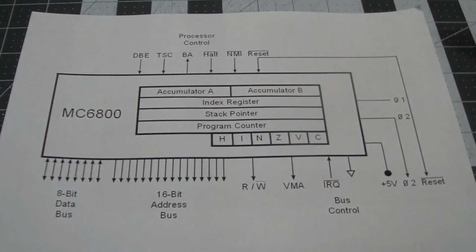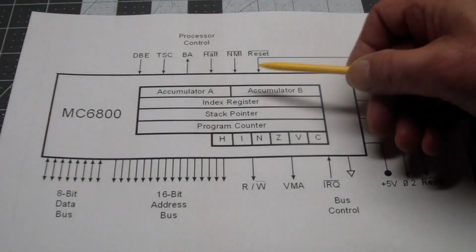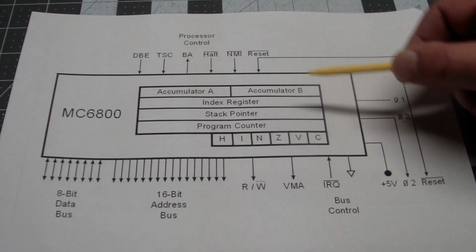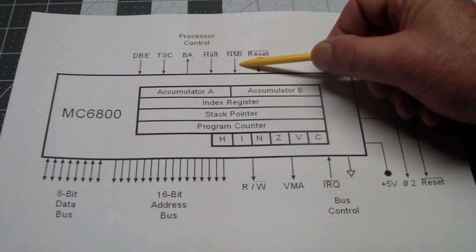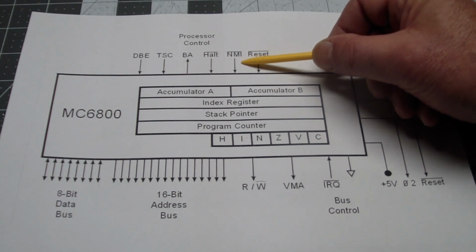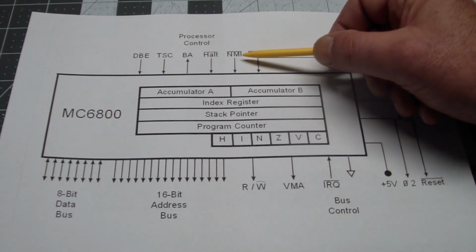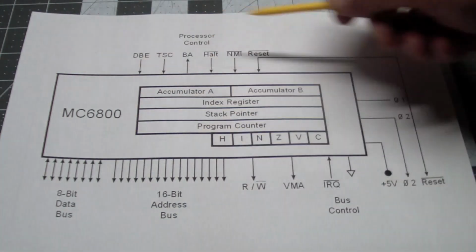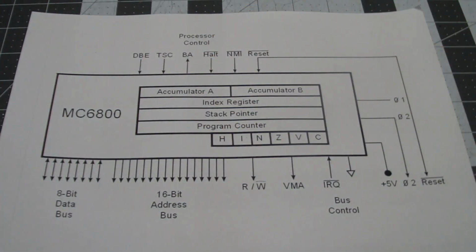It will stop whatever it's doing, whether it's running foreground code or actually already in an interrupt, and again jump to a fixed location and execute high priority code that is the highest priority in the entire microprocessor.